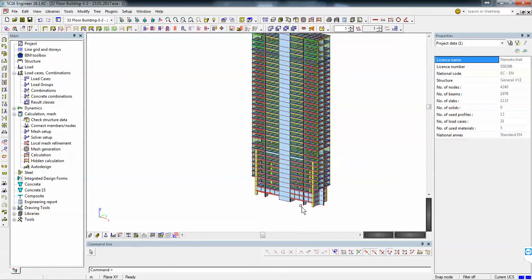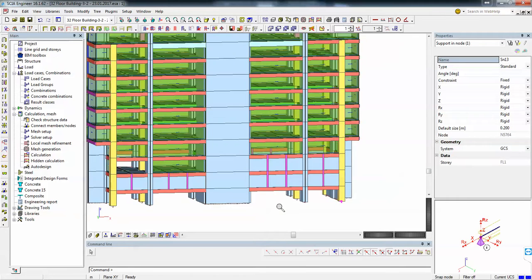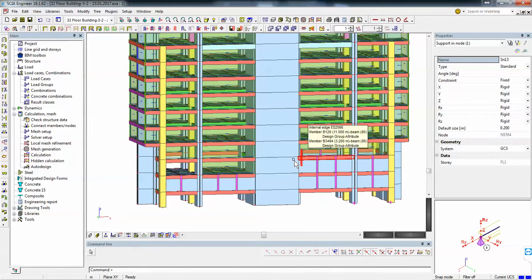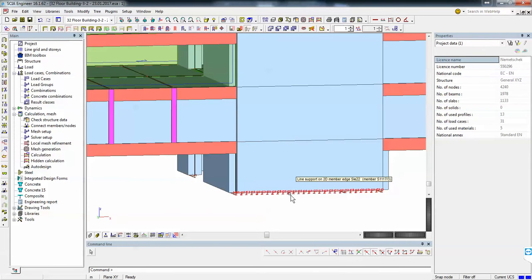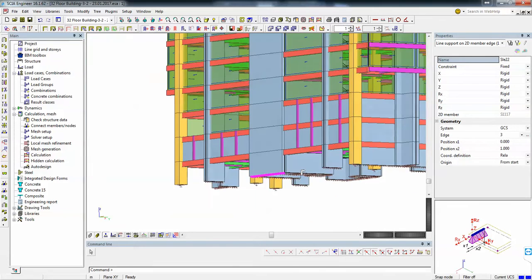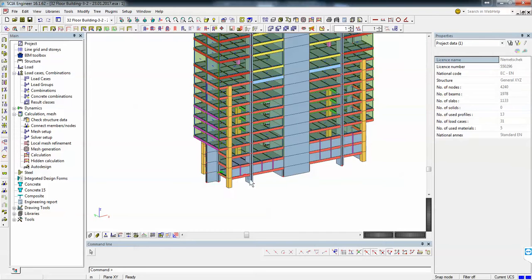Okay, so this is your model. We discussed it before that the ground level is variable, so you have here the soil and it goes down on this area, and you considered it to be fixed here, which is, let's say, conservative. It is a conservative approach, and then we'll place the rafter.